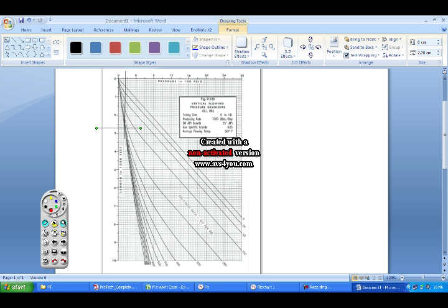Now, if I measure from this depth down 6000 feet, my tubing length, it will give me approximately 8700 feet. So this depth here. The intersection of this depth with this 400 GOR curve will give me the bottom hole pressure which I need to have if I want to produce 1000 barrels of oil per day, and if I want to keep my wellhead pressure at 160 psi.